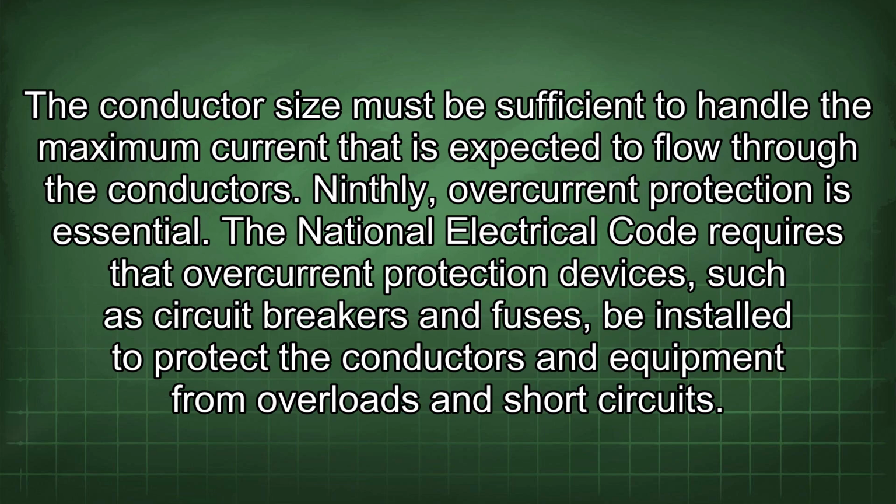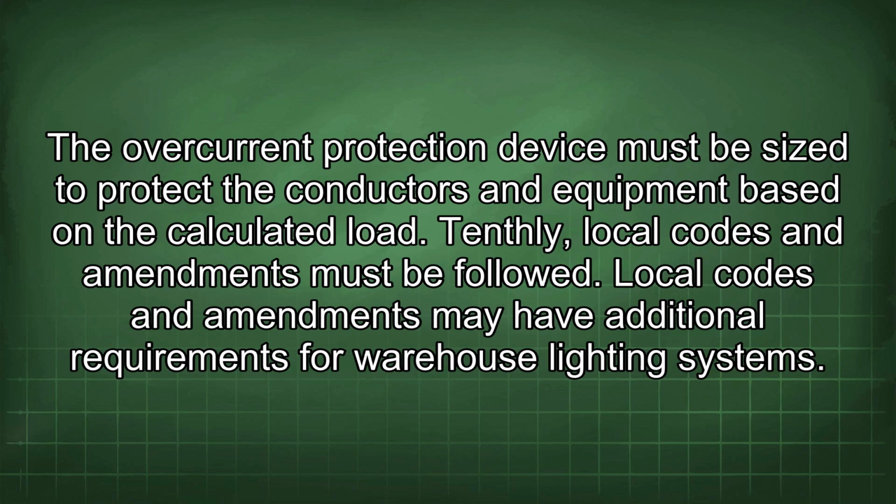The National Electrical Code requires that overcurrent protection devices, such as circuit breakers and fuses, be installed to protect the conductors and equipment from overloads and short circuits. The overcurrent protection device must be sized to protect the conductors and equipment based on the calculated load.